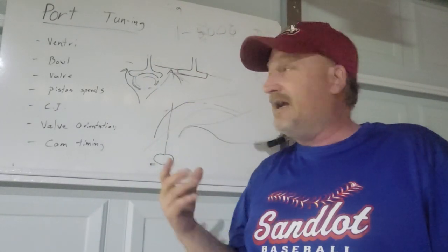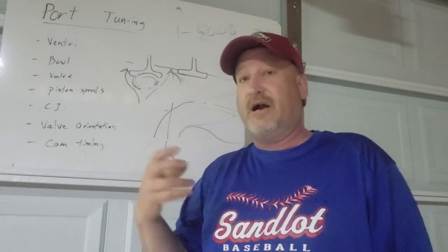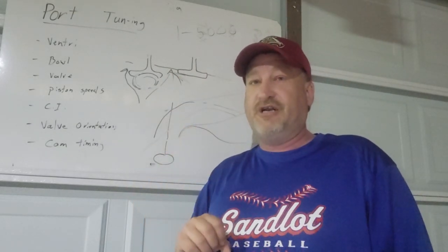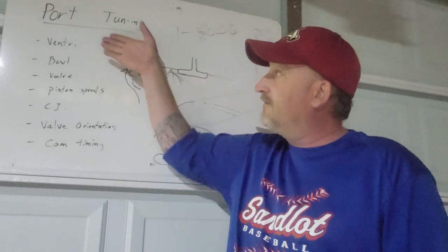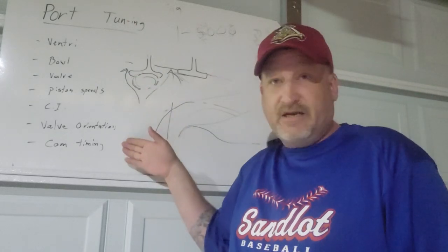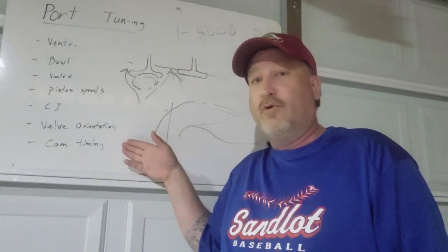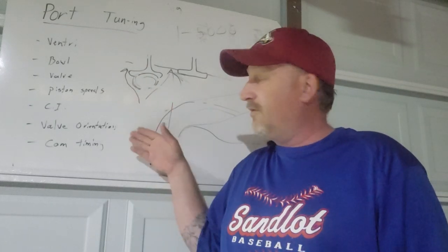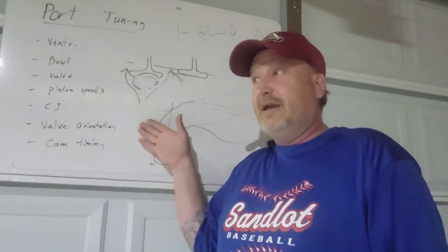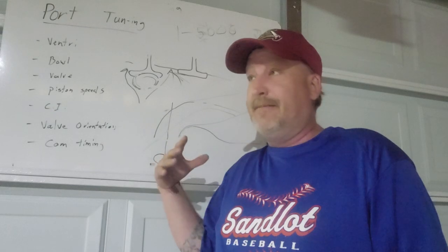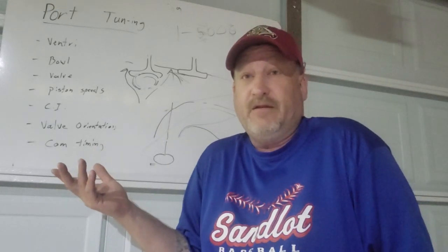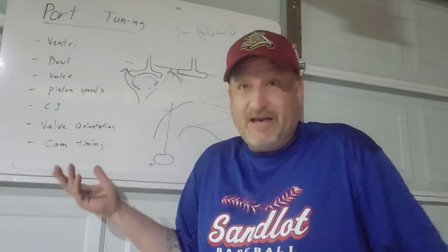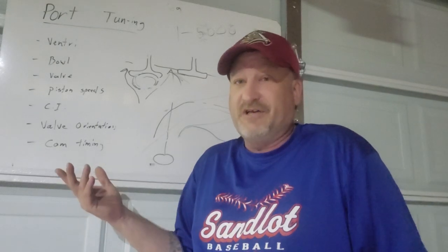So little telltale signs of even the condition of your valves or the carbon printing on the combustion chamber will tell you if all of these mechanisms are actually working together the most efficient. You will also see on dyno or performance test, engines in that orientation will achieve the maximum power that they're capable of making. You can't get any more out of them without going to forced induction.